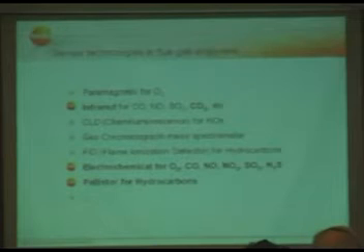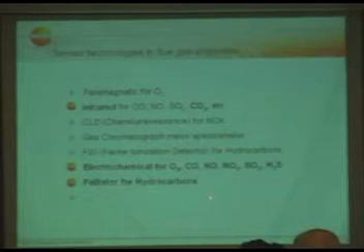You have to calibrate them all the time as soon as you change the location because there are different ambient conditions, like the temperature has changed, the ambient pressure, the absolute pressure has changed. And those reference technologies, they have to be adjusted all the time if you change the location using such an analyzer. And then we have electrochemical sensors for all different parameters like oxygen, CO, NO, NO2, SO2, H2S, and some more. And we have Pellistor for measuring hydrocarbons.